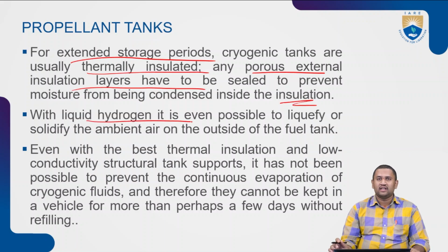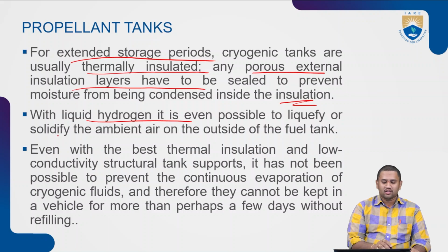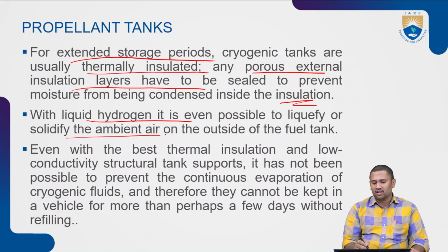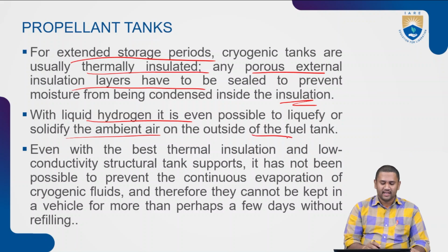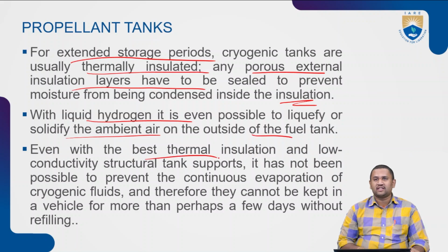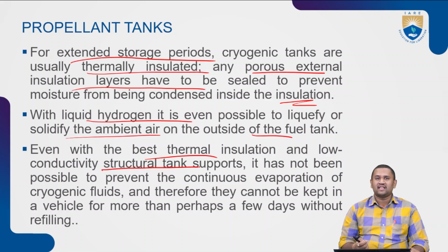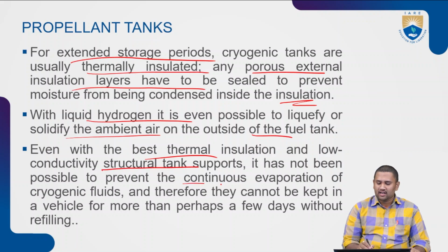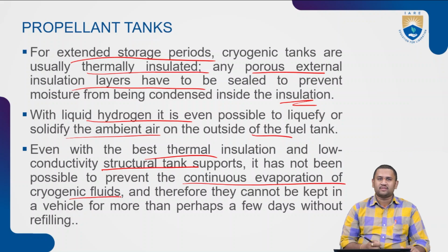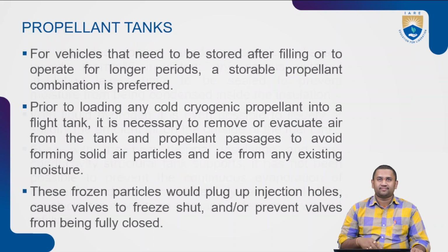And with liquid hydrogen, it is even possible to liquefy or solidify the ambient air on the outside of the fuel tank. Even with the best thermal insulation and low-conductivity structural tank supports, it has not been possible to prevent the continuous evaporation of cryogenic fluids, particularly liquid hydrogen, and therefore they cannot be kept in a vehicle for more than perhaps a few days without refilling.